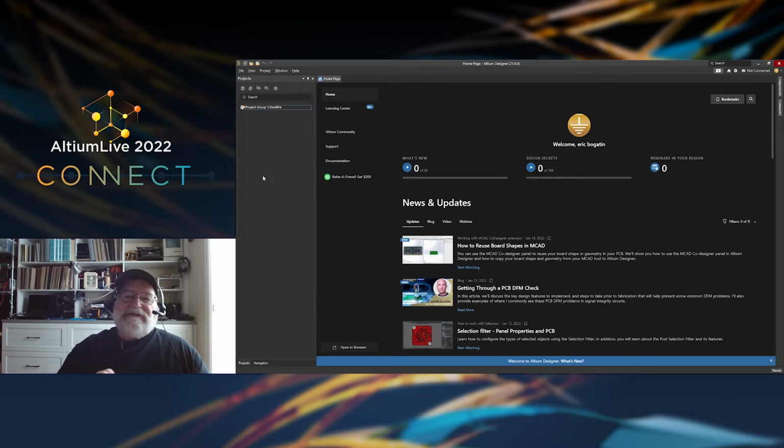Okay, once you've had a chance to look over some of the interesting content that Altium has provided, now we're going to begin using the 2D field solver. And to do that, we have to have a PCB page or layout open so we can access the menu-specific items for that page. So I'm going to come over here to the project.